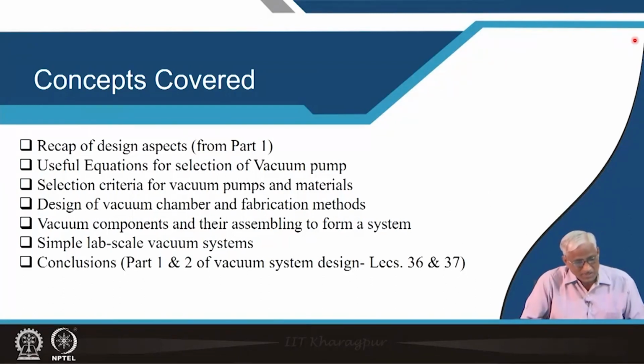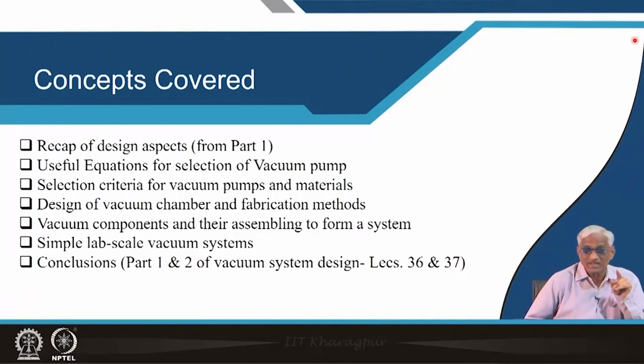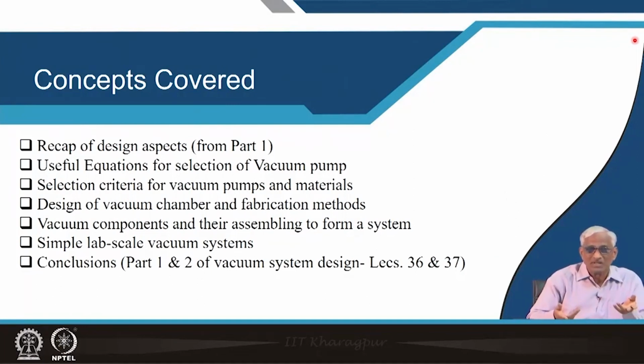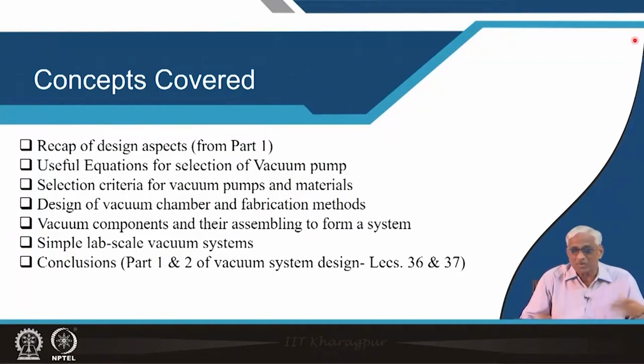So, those design aspects we will see at component level as well as chamber level, including fabrication aspects as per your design. You cannot leave fabrication aspects to some mechanic, you have to tell as a part of your design, okay. Whether it is brazing or welding, you have to design. If you say okay, you connect somehow, they will put some adhesive and you will not get even 10 power minus 5 torr, when the system is supposed to get 10 power minus 8 torr, though the pump is good, the chamber is good. So, you have to also keep track of fabrication issues.